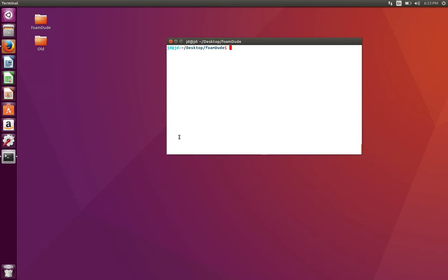We are going to start by copying one of the tutorial cases and start looking at the BlockMeshDict file, and we will see how to use BlockMesh in the next several minutes. So I'm going to start by copying one of the tutorials from incompressible cases for icoFoam, and we are going to grab the cavity case. I'm going to put it in the parent directory.